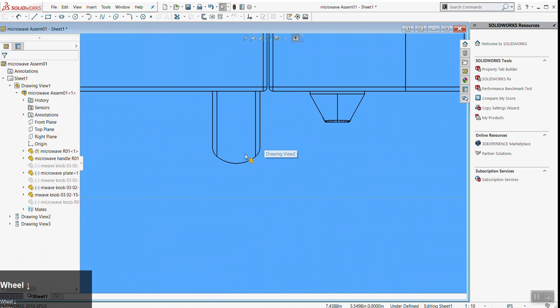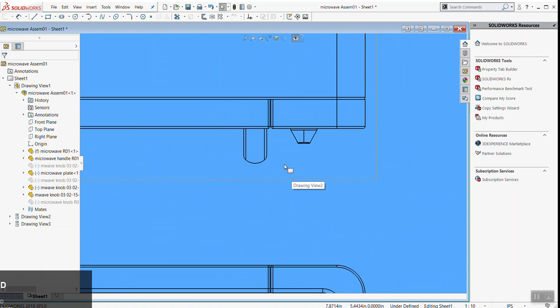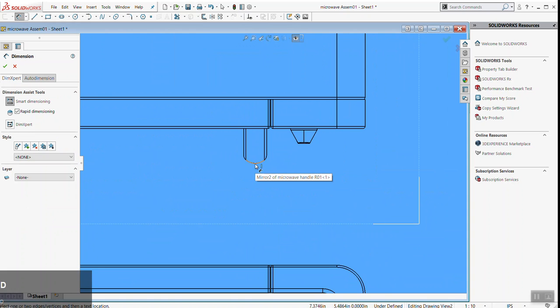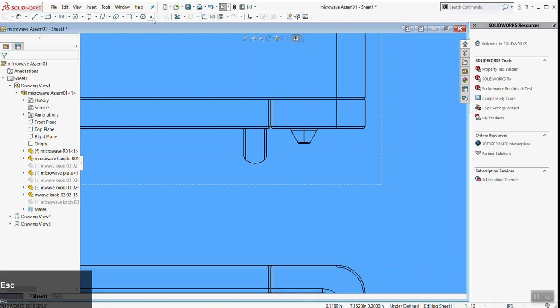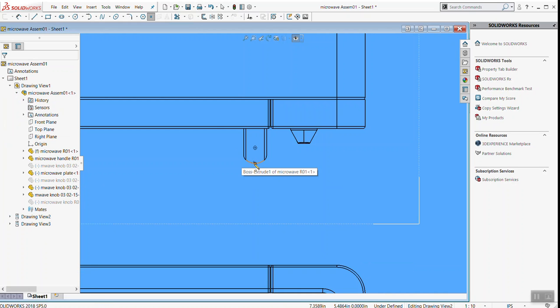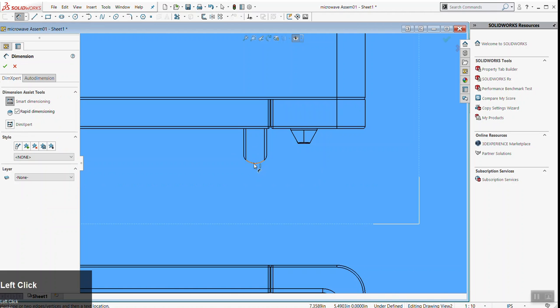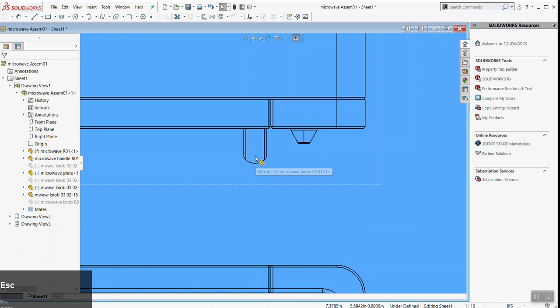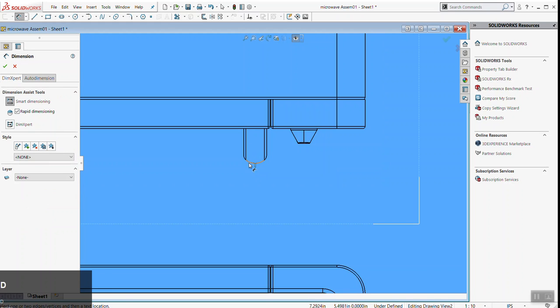Now this one's a little bit trickier. If we're getting the overall dimension, technically we should go to this widest part with the handle. And you'll notice there's nowhere for me to grab here. So one thing you could do is you should see a sketch dialog at the top here. You can select a point. Now if I hover over here, it should give me a center point to snap to. I don't think it gives me that with a dimension. Yeah, for sure. So you'll notice with the dimension, there's nowhere to snap to on the arc.